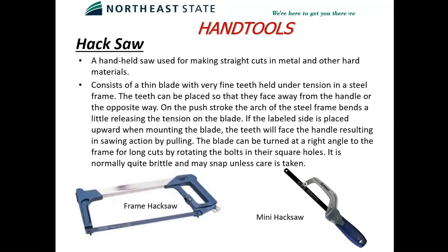Cutting tools, we've got hacksaw, different frame sizes of those. Different manufacturers make them a little bit different, but they're all essentially the same blade. Your blades can come in different numbers of teeth. You can get them for like 32 teeth per inch, or TPI, down to like 12 teeth per inch for cutting wood, and 32 teeth per inch would be for cutting thin metal.